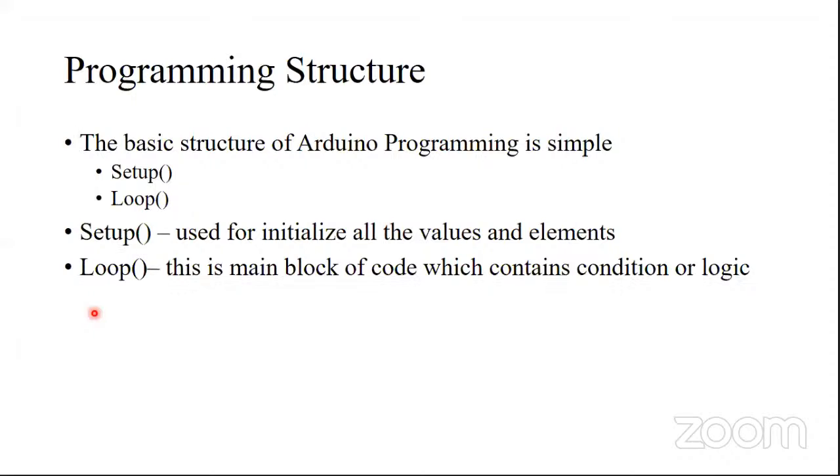So again, coming back to the selection of Arduino board. When you are selecting your Arduino board, if you are planning to give 2 or 3 inputs, the normal Arduino Mini or Arduino Nano is more than enough. But when you are going to give multiple inputs, more than 5, 6, 7, we always prefer a Mega or Lilypad, those kinds of boards.